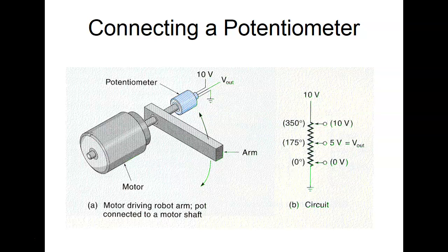We've got one on the Festo line, and we've got one on the Amatro line. What they do is they have a cylinder, and they raise it up, and they have a flat thing that goes over to a potentiometer. When it comes up and hits that thing, it moves the pot, and the pot gives us a voltage that represents the height. And then we're using that.